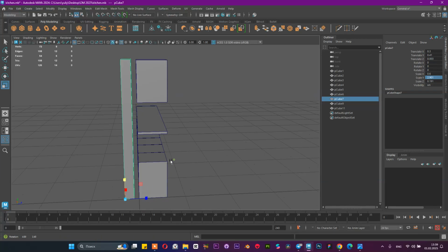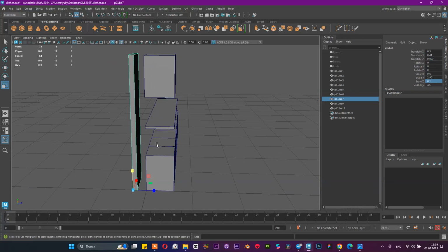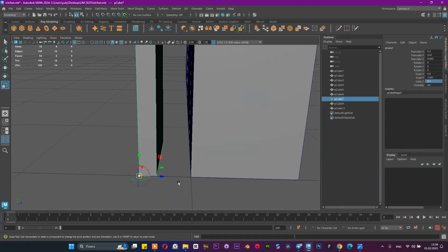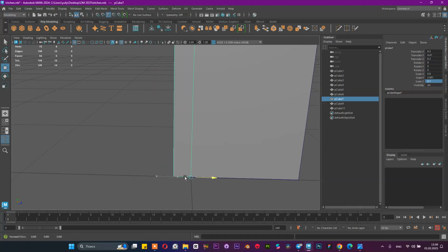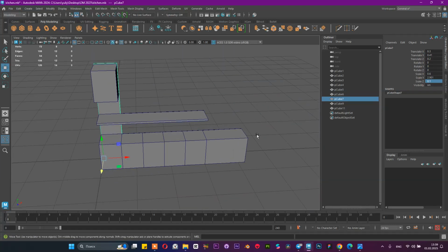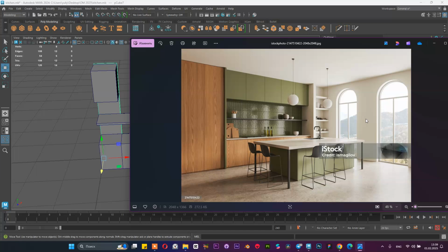Here we have our wall. First wall, we have 10 centimeters width for the wall. It's almost standard parameters, and we can start making some walls. Let's change this pointer to another side, and I'm going to use again pressing V on the keyboard and snapping with the objects. And let's increase the size of the wall to the end and here.